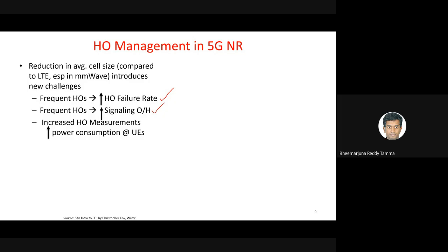Your user equipment is supposed to listen to all these different channels to decide which channel is better, if the operator is licensed to operate on all of them. That has a negative impact on the power consumption at the user equipment, because it has to do channel state estimation on all the frequencies on which the operator has a license to operate base stations.